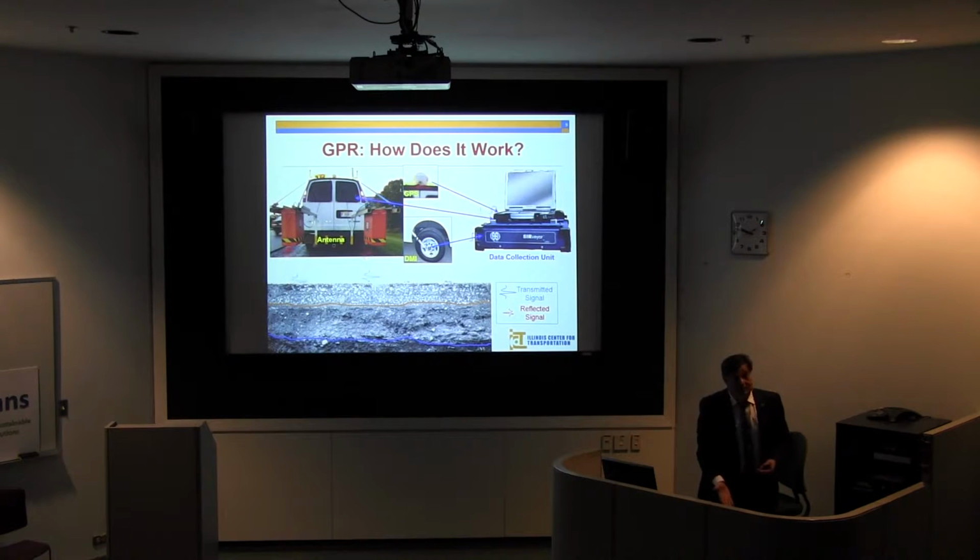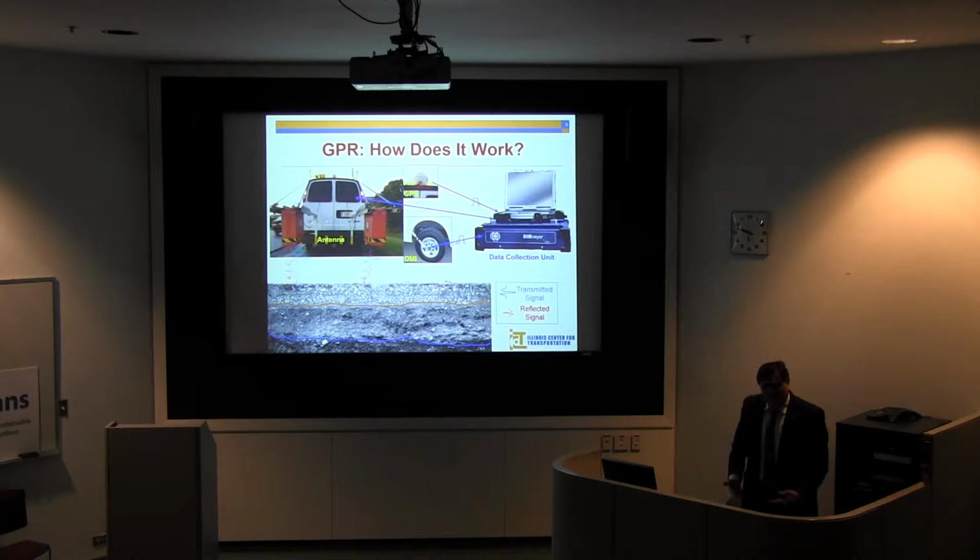It will go through the material, the first layer. When it gets to another material, it will have a different dielectric constant. You have another reflection, and during that time, you lose some power. So it just keeps going. Whenever there is a different dielectric constant, it will reflect back, okay? But at the same time, you are losing some power. So at a specific depth, you start losing complete power and you are not getting anything back, okay?